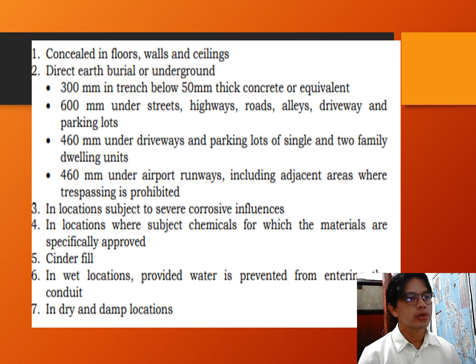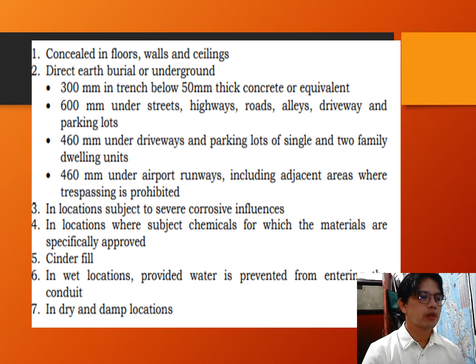600 mm under streets, highways, roads, alleys, driveways, and parking lots. 416 mm under driveways and parking lots of single or two family dwelling units. 260 mm under airports, runways, including adjacent areas where trespassing is prohibited.